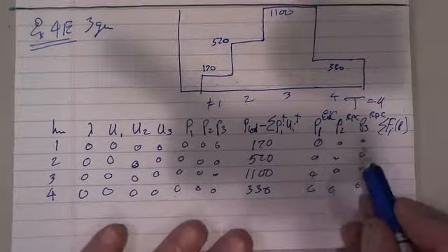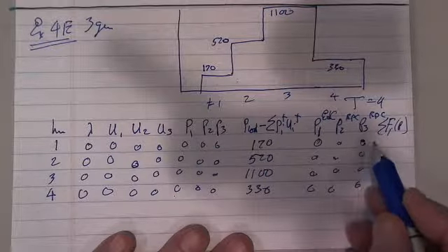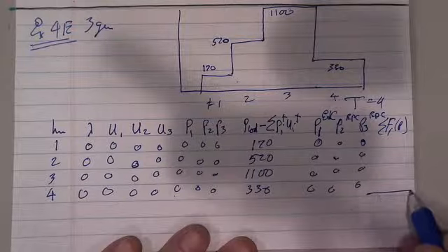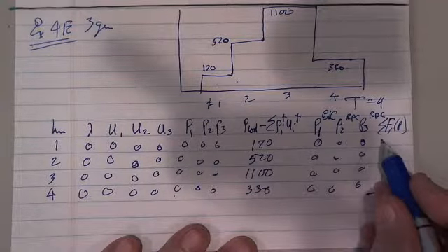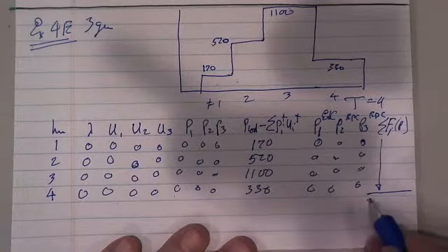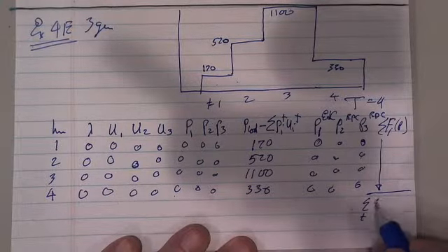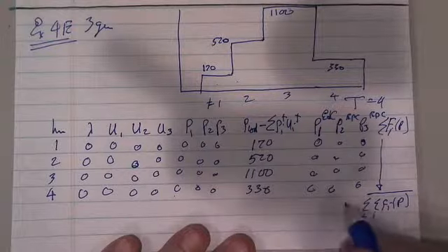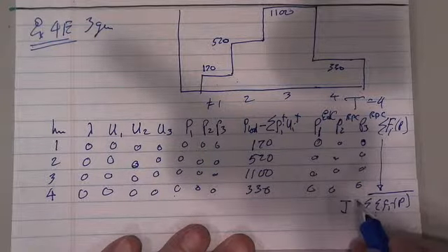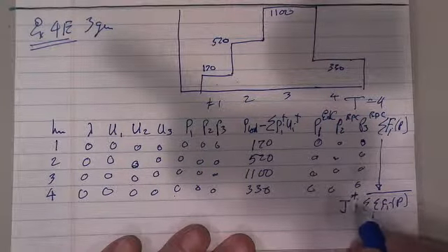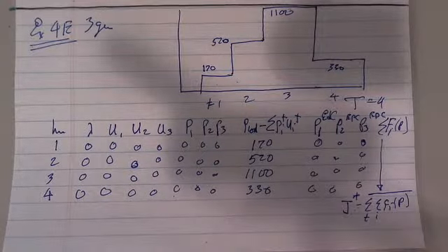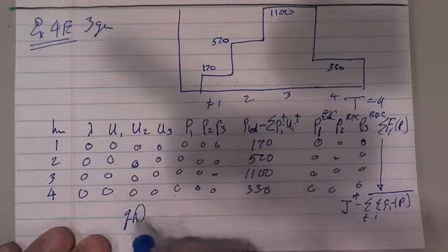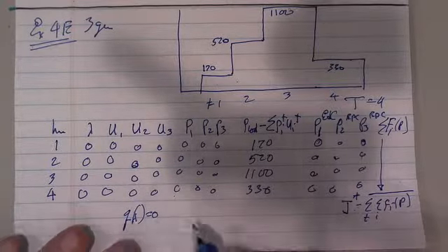And I would sum the economic dispatch solutions costs, and then at the bottom I would sum all of them. So I would sum all of that, and that's the sum over T and the sum over i of Fi of P. This is at the economic dispatch. We called that J star. Okay. And it's easy to figure out what the value of Q and lambda is. It starts out at 0.